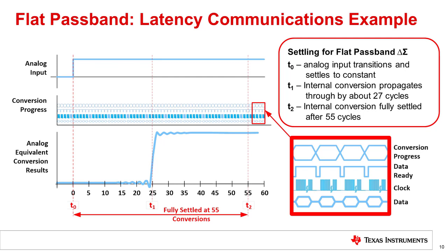This delay and settling may seem excessive, but keep in mind that this type of converter normally will not be used to capture multiplexer outputs or DC transients. Rather, this converter will be used to capture AC sinusoidal signals. In this case, the converter will simply introduce a group delay, but the impact of this delay may not be significant. Let's look at a datasheet excerpt for a delta sigma converter using a high latency filter.